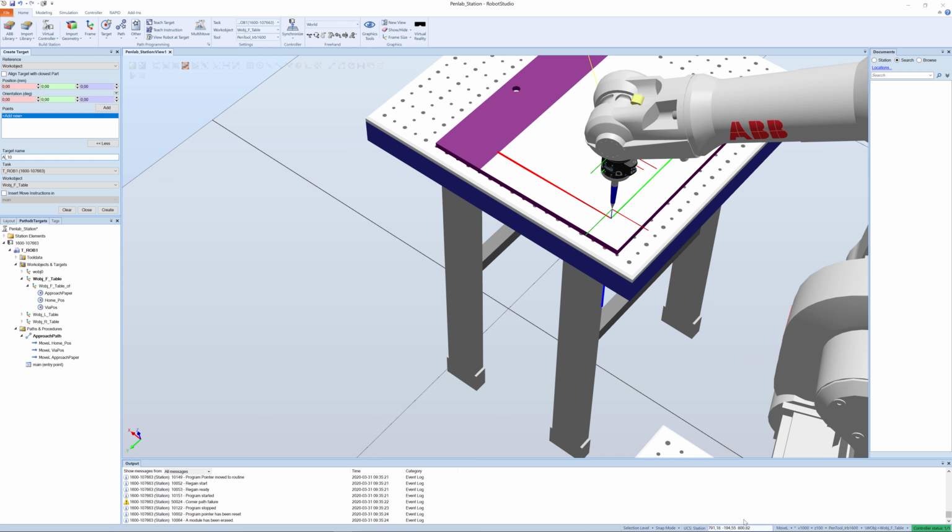What we can do already now is change all these to 100, and we change the set value, which is a zone, to calibrated corner points. We set it to Z1 at the moment; we can change that later on. That's fine. And then we start with adding points. That is the first one.